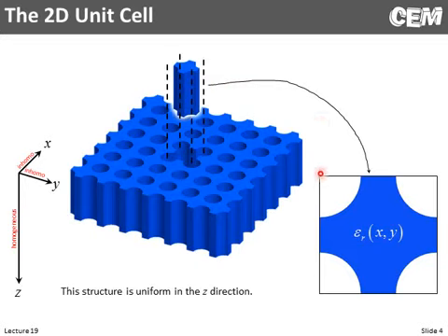So down here we have a cross section of our unit cell, and this really is representative of a three-dimensional device that we're showing up here. But in rigorous coupled wave analysis, we're going to analyze the cross section numerically on a grid like we're showing here, and then in the longitudinal direction we have an analytical solution exactly like what we did for the transfer matrix method.